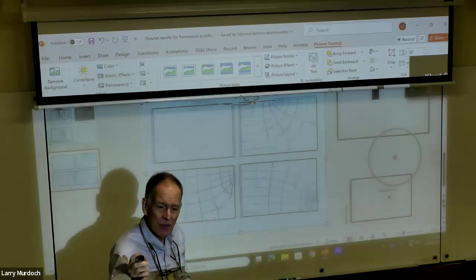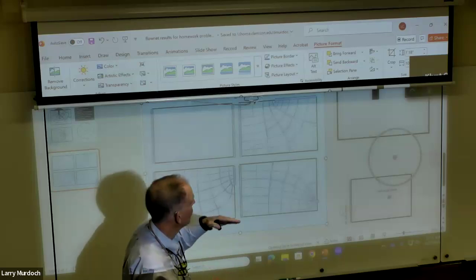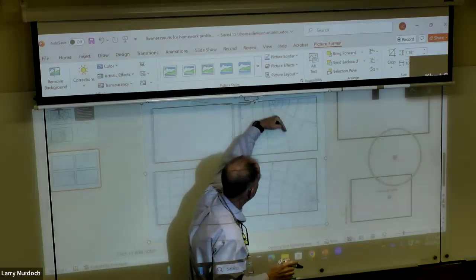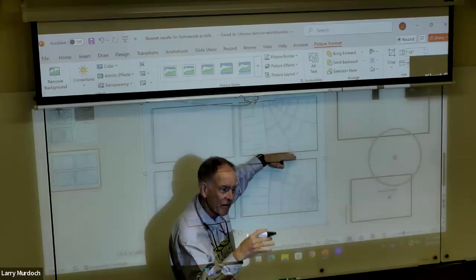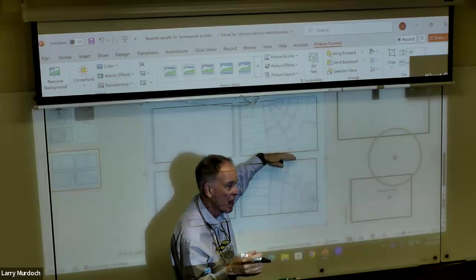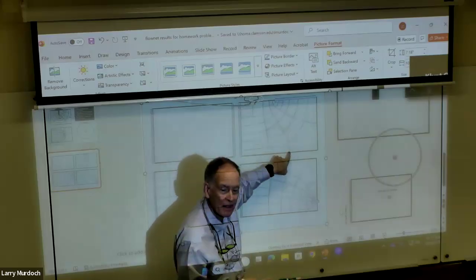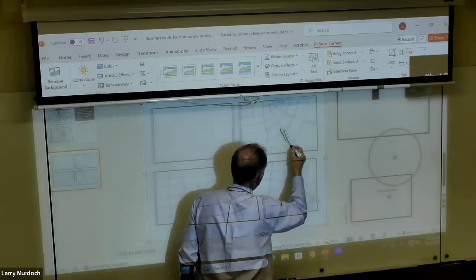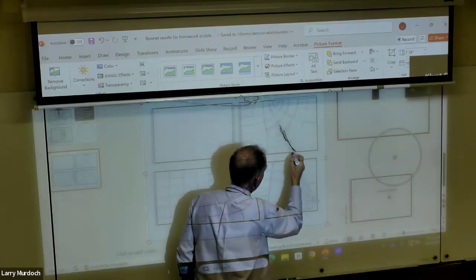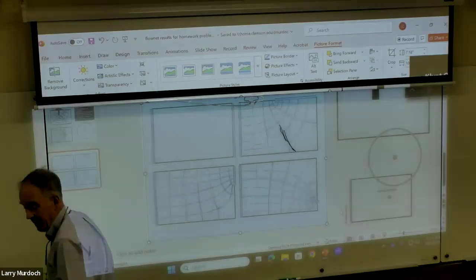One thing that I saw a lot that I want to make sure everybody's aware of: that rule applies for the streamlines and the equipotentials, but the no flow boundaries also behave that way. We consider them like a streamline. So the equipotentials, when they come into the boundary, have to be perpendicular. A lot of times people were drawing it in and it would just kind of go like that. But it needs to hit that boundary and be perpendicular.